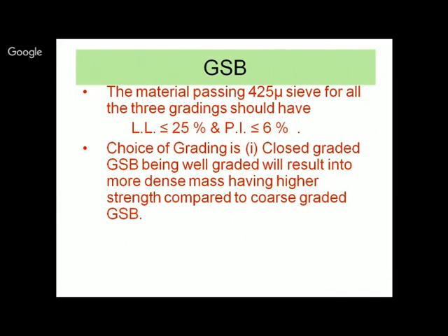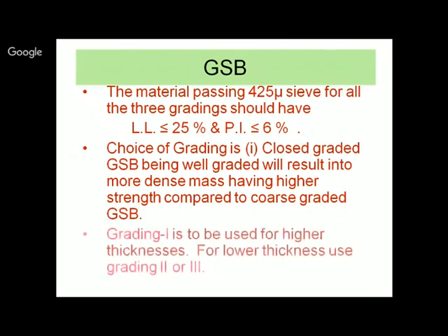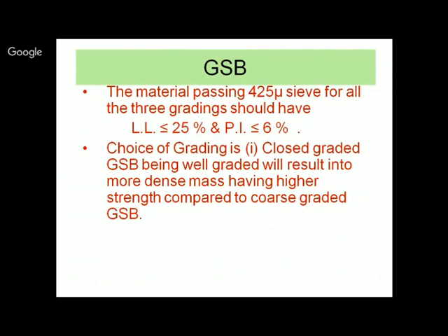Now if I practically speak of the requirement, then I would rather say that if you are going to build up an expressway or national highway, or say even a state highway, which is going to cater to a very large volume and weights in terms of the traffic requirements, so I would be looking for a well graded material, because I look for a very high performance from that.